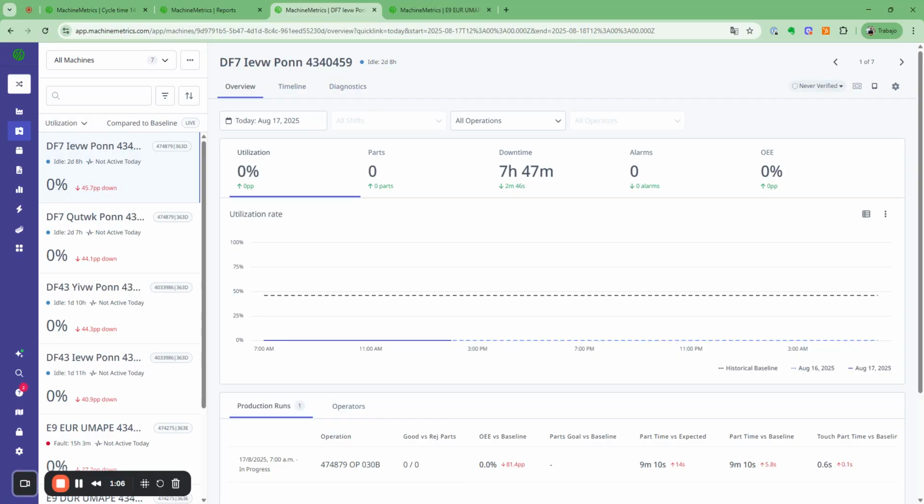show us not only the highest volume part number that we are producing, but then we're going to zoom into that part number and understand how the cycle time has some changes and variations that we probably would assume don't exist when we are using these ERP average standards. We tend to think that we have a pretty standardized cycle time, when in reality, machines can have some variations, and these variations in cycle time can represent at least a 10% difference in your performance.